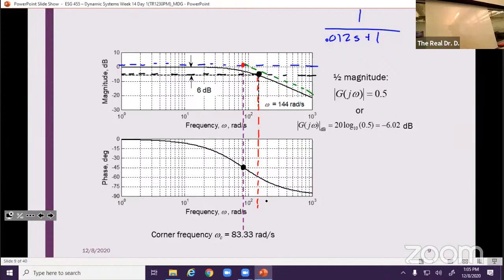So far, what have we seen? What can we do with Bode plots, right? You can determine the steady state response given an input function from a Bode plot, right? Because if you can figure out G of j omega, which is just my magnitude, all you have to do is convert it from decibels back into unitless, and you convert degrees into radians, right? Just read it right off the plot at the specified frequency.